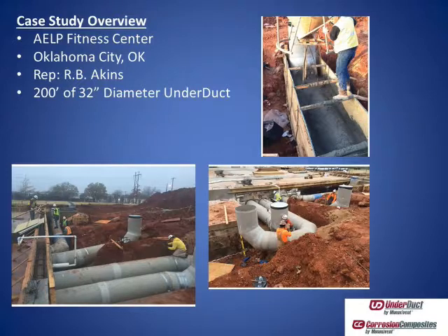And for that reason, since it's not under a slab, these ducts were concrete encased. And it's not required, but in this case it is, because we don't have a slab over it. It's underground and you could drive a truck over it or whatever. So if you look at the photos here, you'll see the guys putting the duct in and they penetrate the wall. The concrete is being poured on the top photo there, and they did encase all of these exterior ducts completely in concrete.